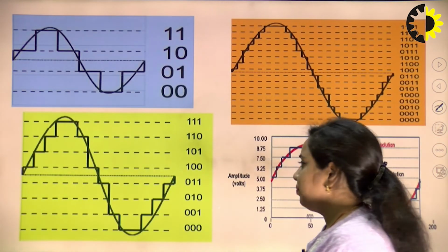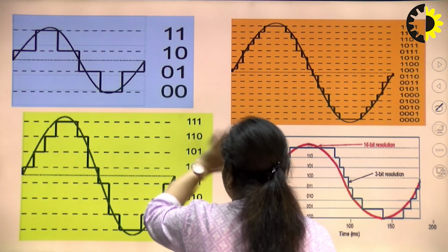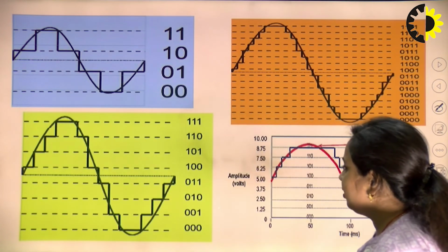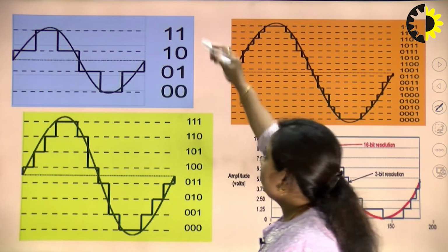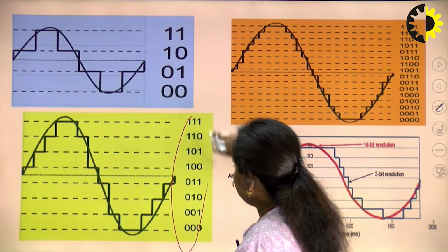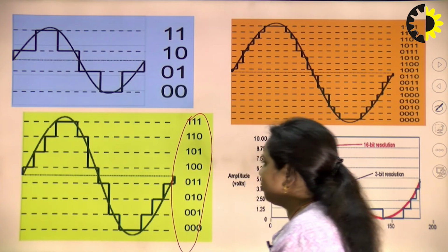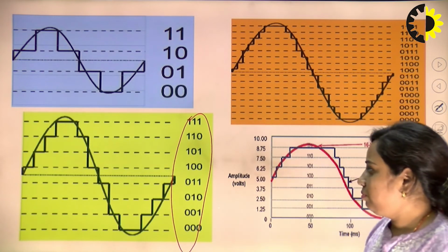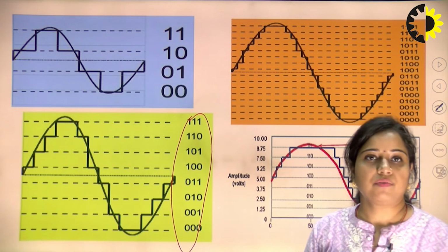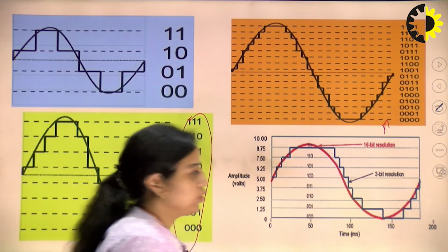Next, this diagram is basically showing that when we have considered 2 bits of encoder, like 00 to 11, 4 options are there. That only depends upon the dynamic range of the input signal. Now, when we have considered 3 bits, like 000 to 111, this is how the dynamic range will be divided, and this is how we can generate a staircase approximation of the signal. Next, we have considered V equals 4.